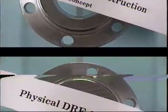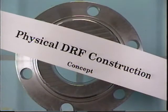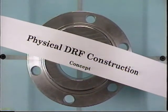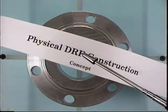And so you can set the datum reference frame to use in many applications. In CAD, in design, we use it for visualization. We also use it for measurement. And in manufacturing, the physical datum reference frame construction is everywhere, and we use it to define the x direction, the y direction, and then of course the z direction, which goes in and out.